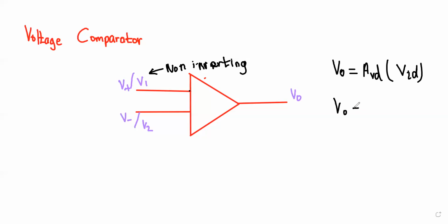That limit is Vs, the source voltage, or you can write it as VCC. Normally we will mark it on this side. This is going to be minus VCC, and it can only increase up to this V source, or plus VCC.